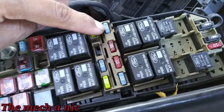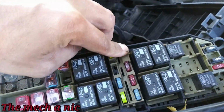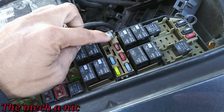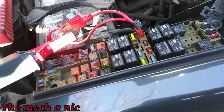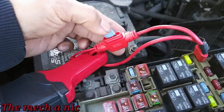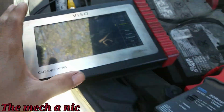Get this out the way. It's going to correspond to this blue 15 amp fuse for the fuel injector. So that's the one we're going to check. And by check, I mean put our current clamp on it, not check to see if the fuse is blown, because obviously the fuse is not blown, the engine runs. Alright, so as you can see, I removed the 15 amp fuse and I put it in right here using my current clamp, and it's connected to the scope already.